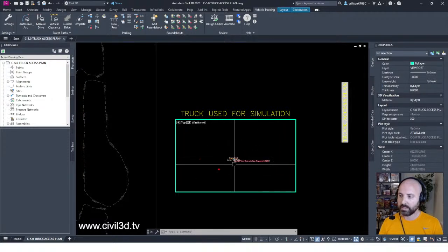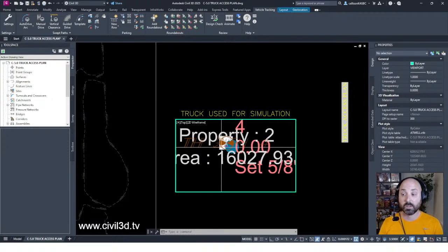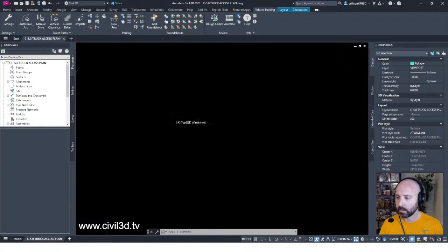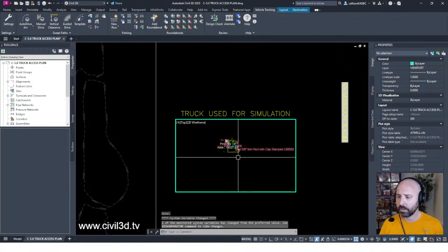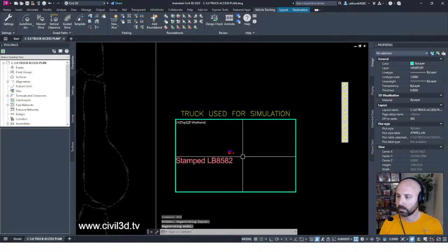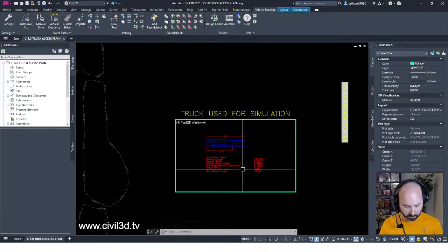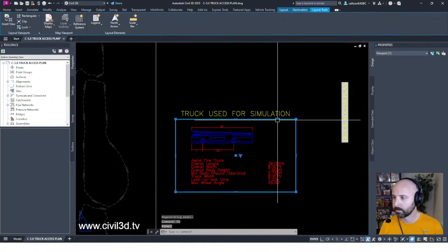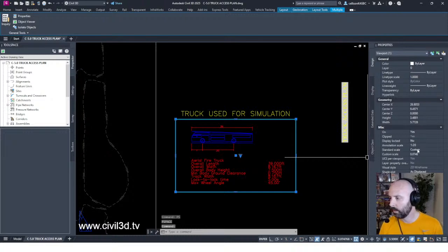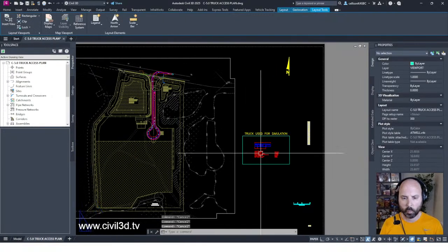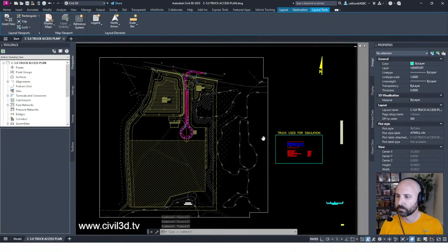What I do is I basically zoom into where I have an idea, where I see a bunch of stuff happening like this, and then I type in regen all, REA. And that'll begin to shrink things. REA. Here it is. Begin to find it. And then for the standard scale, I'm going to go with 20. And there you go. And that is essentially it.